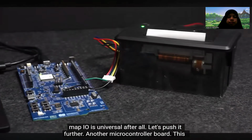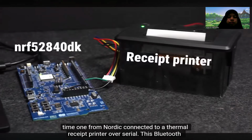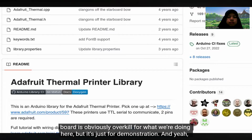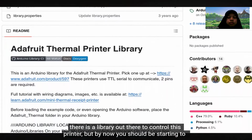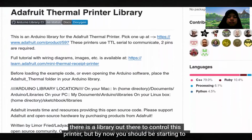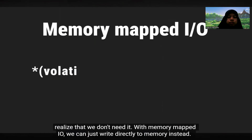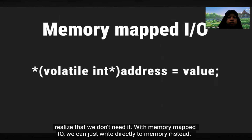Let's push it further. Another microcontroller board, this time one from Nordic, connected to a thermal receipt printer over serial. This Bluetooth board is obviously overkill for what we're doing here, but it's just for demonstration. And yeah, there is a library out there to control this printer, but by now you should be starting to realize that we don't need it. With memory mapped I/O, we can just write directly to memory instead.